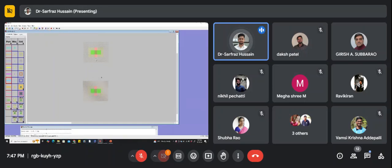Now you can connect these polysilicons all together. You can bring this one closer and connect these polysilicons. Leave some space, because if you don't, there will not be any space for connecting the wire. You need to give sufficient space so that you don't violate the minimum design rule, so in order to go with the minimum design rule, leave some space in between.